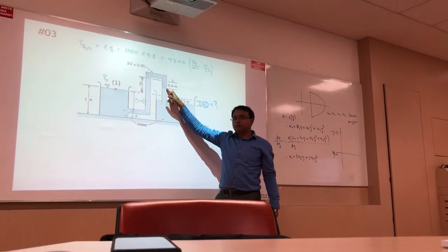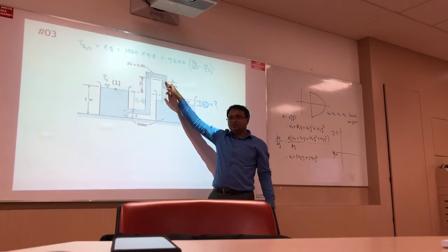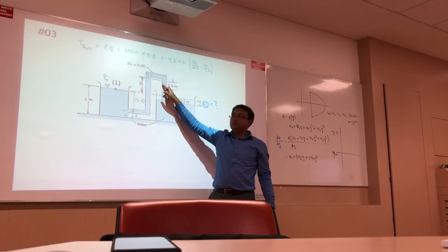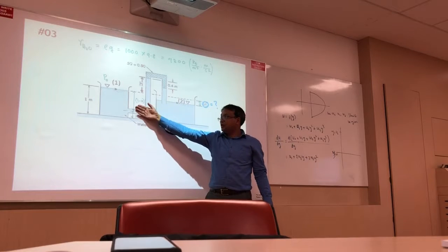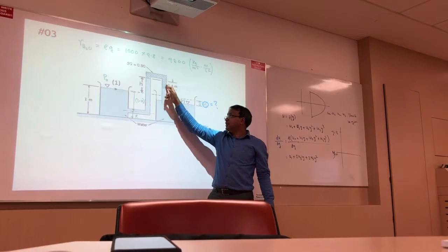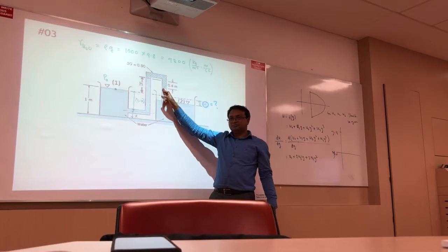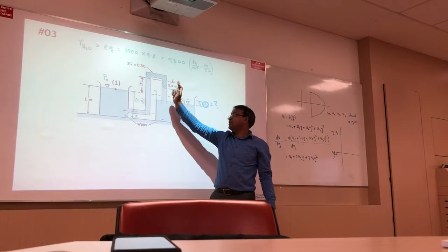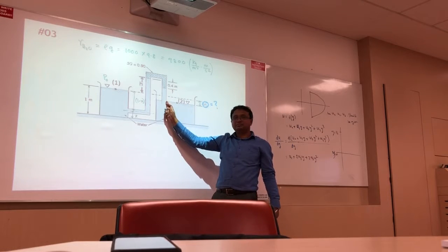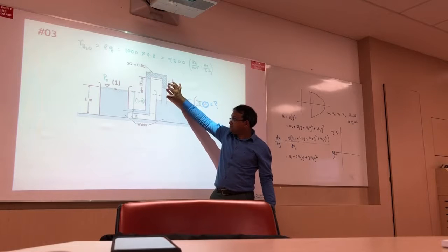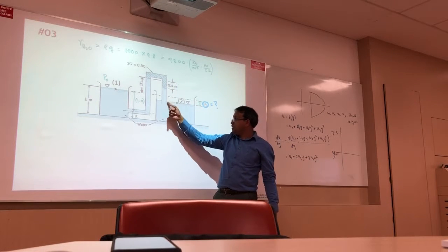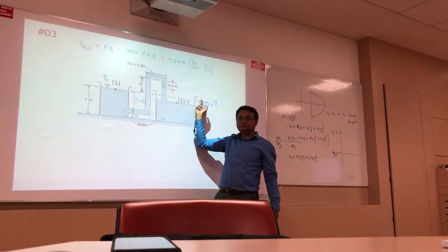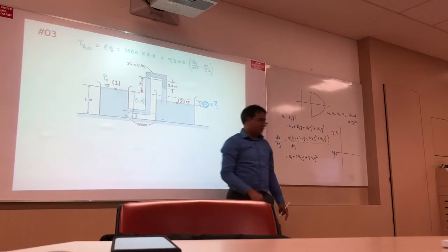From here to here is 0.4. That means plus rho G. No, specific gravity is there, different fluid. Specific gravity is 0.9. There is water, 1. So rho g h times specific gravity 0.9. And from here to here, h minus 0.4. From here to here, delta h. Right? Now you can see how I solve this.